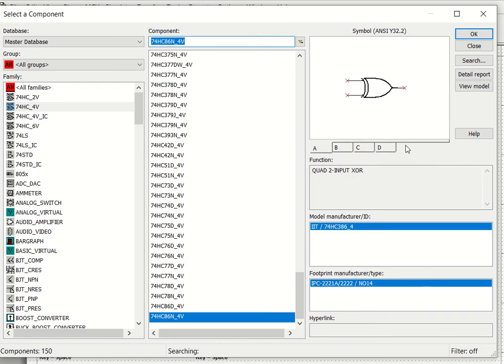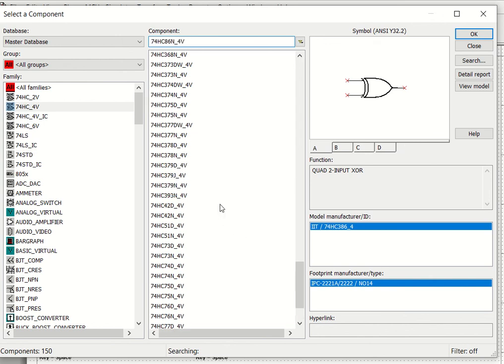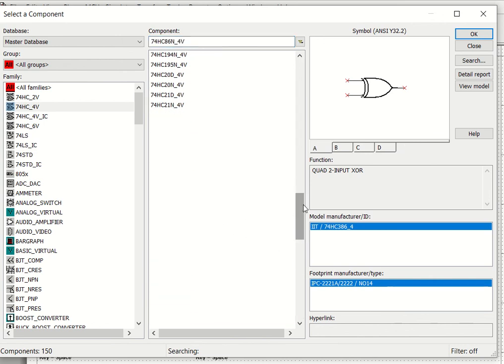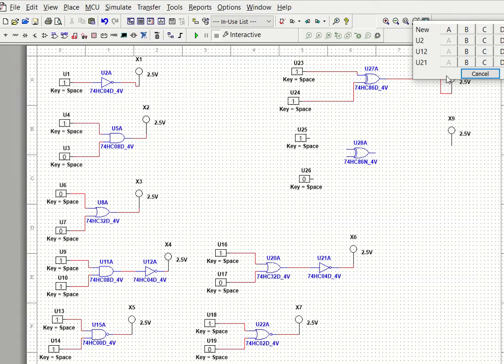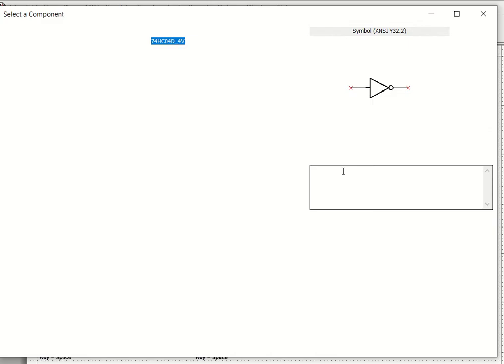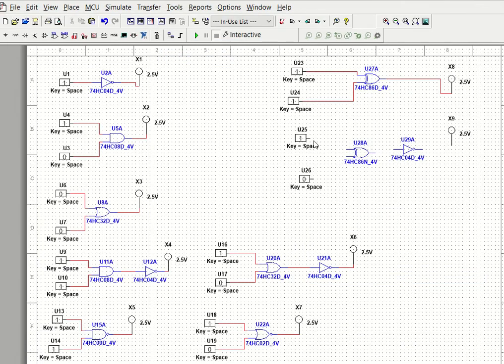If you take the complement of XOR, you can easily see that the result was XNOR, isn't it? We have seen that previously. So we will try to do that here as well. 7404, let's bring. Okay, 7404, and we can just connect the wires.